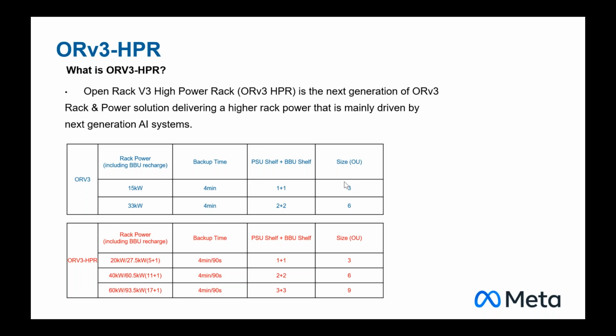Any other questions for David? If not, I have a question for David Moore. David, I know David Sun just mentioned we are reaching 24 amps per line, approaching close to 5.5 kilowatt. Are you looking at this application at 230 volts / 240 volts or 277 as well? I'm just worried about more derating and the margin we have at the lower end of AC voltage. Right. I base the 5.5 kilowatt ask on really a 60 amp input connector.